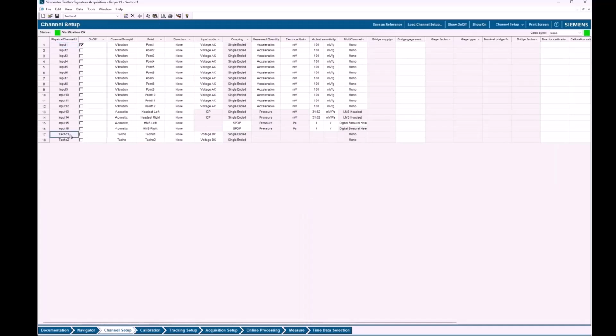But it's also possible if you have a tachometer like this, you can go in here, and if you pick vibration, this is maybe an unknown trick, then you can use it as both a tachometer and a vibration channel without teeing it. That's your, I guess, virtual tee, if you will. Were you aware of that one? Yeah, I was aware of that one. That's pretty cool. And so I will actually still get a tacho channel that will say tacho, and then I'll also get another dynamic channel for this tacho one. Is that right? And the vibration.